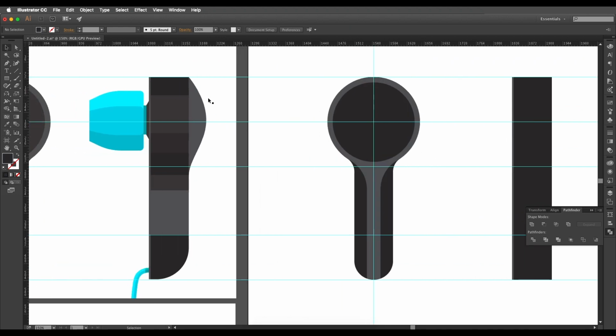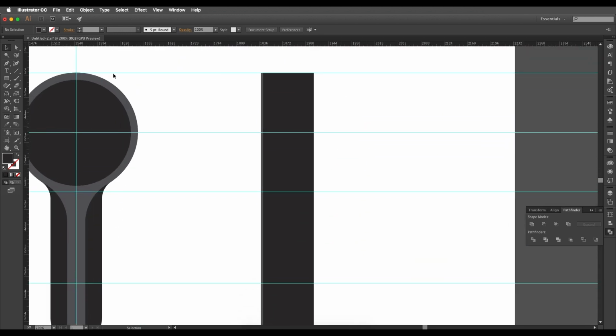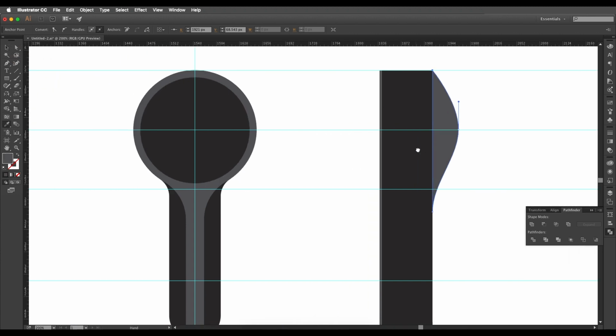And for this side piece, this curve one, I'll use the pen tool to draw out that. So let's select the pen tool and let's draw it out. So just click, and from over here just click and drag and make a curve like that. And over here again just click over here and give some blend with the design, and then with the Alt pressed, click on this point to break the point and then close the shape like that. Let's apply a light color for this.